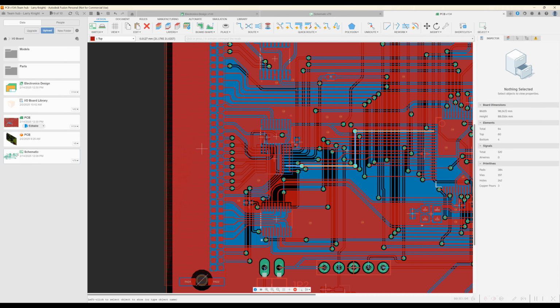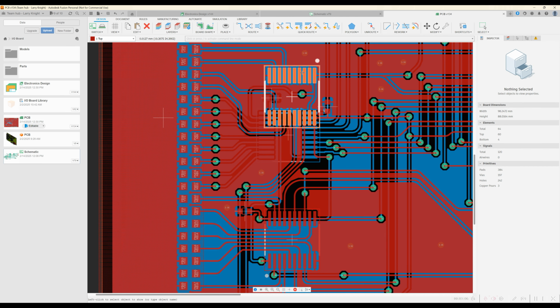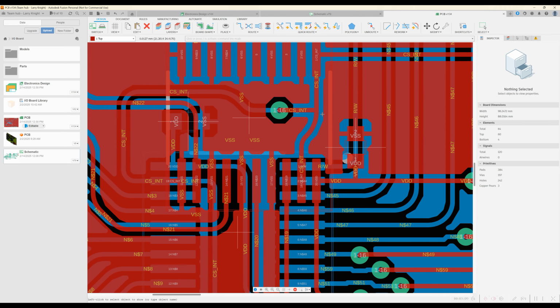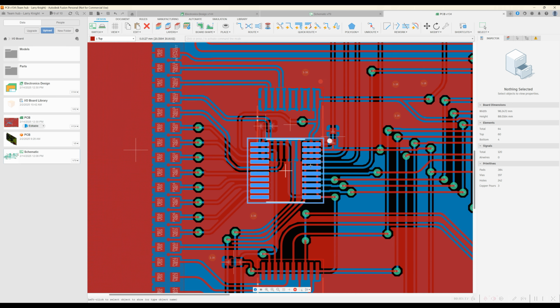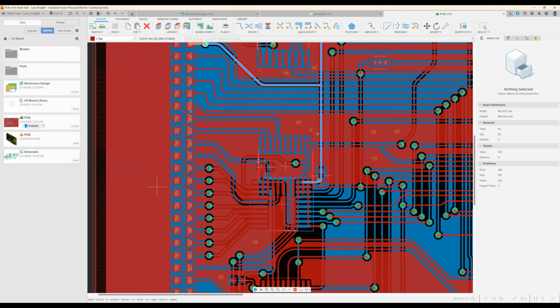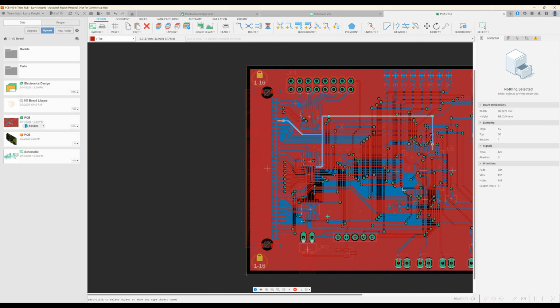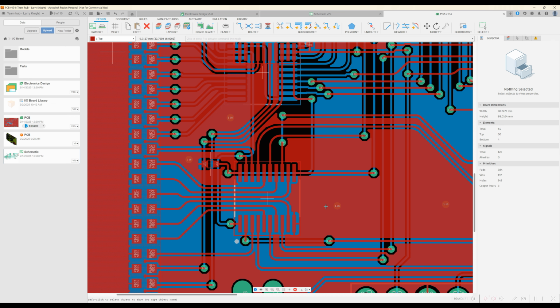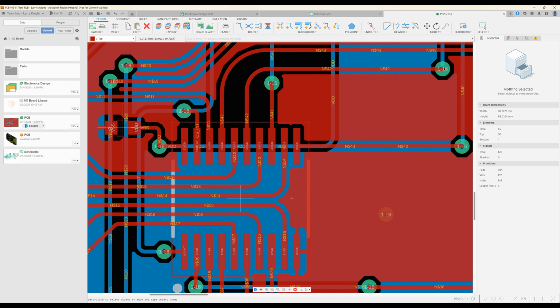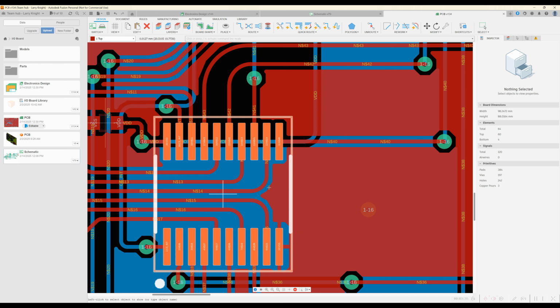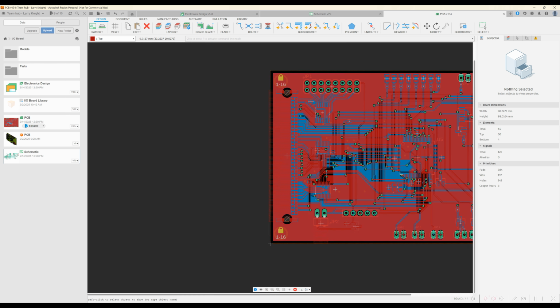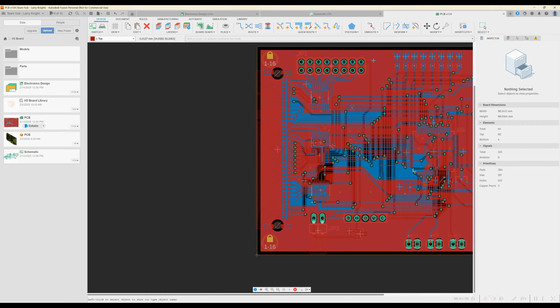Yeah, we can check pin 1, no problem. Are these tied together? Oh yeah, 1 and 19. So we'll check pin 1 and do the resistor trick, and that will tell us pretty much what we want to know.